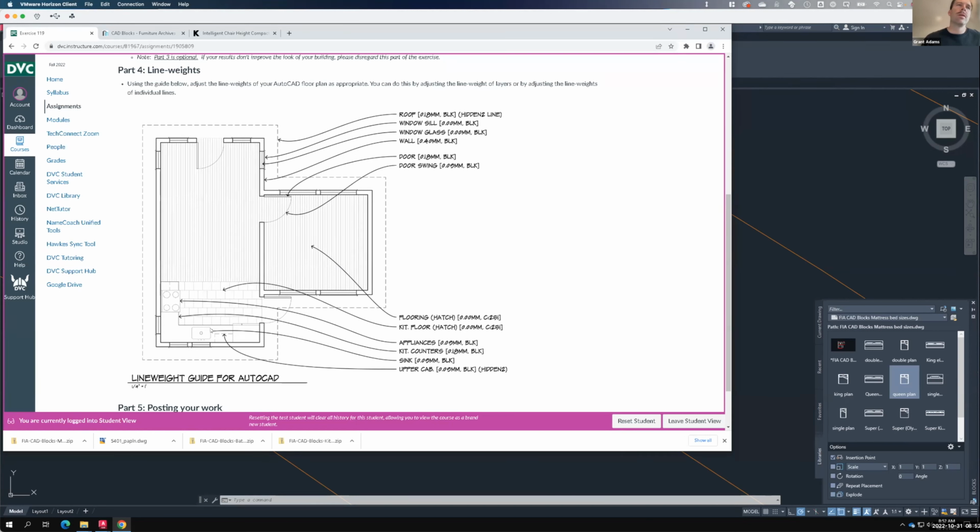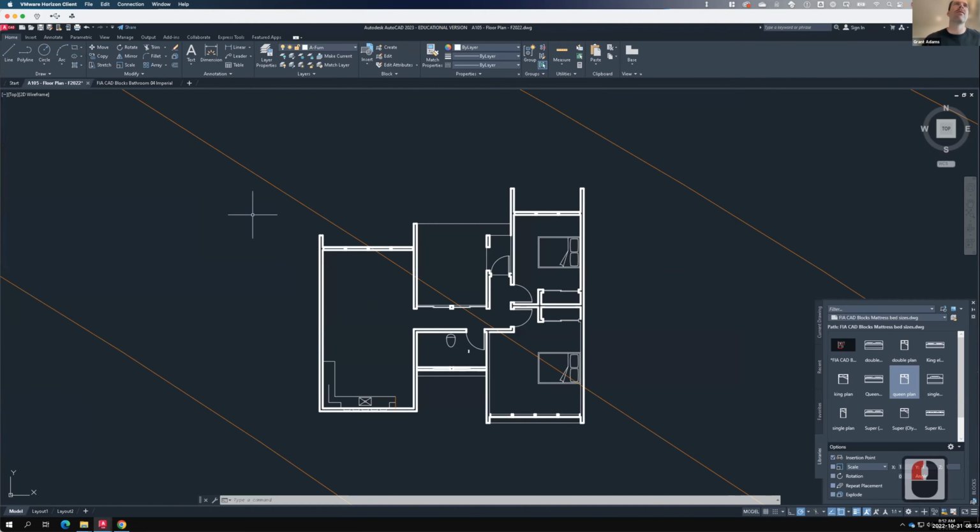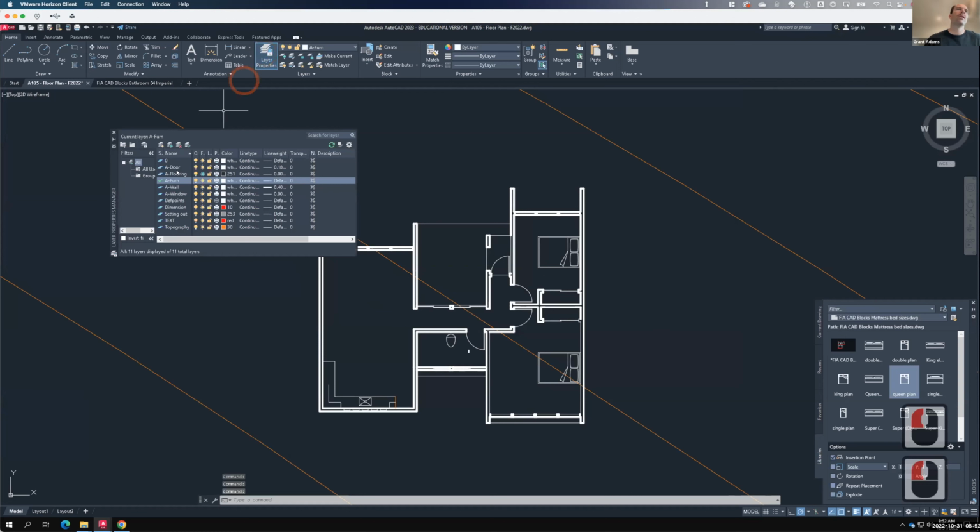There are some dashed lines in here. So I had upper cabinets, for example. I had this roof line. And when I refer to those, you can see that I have hidden too listed. That's just that line type. So if I went back to my fixtures layer, which I don't have, that would be where cabinets would go. So let's go A-fixture.